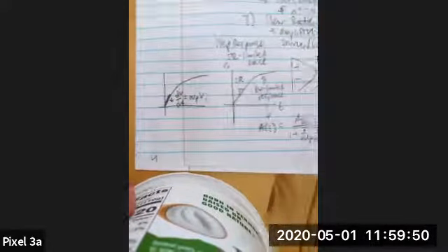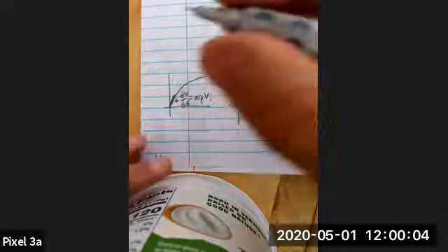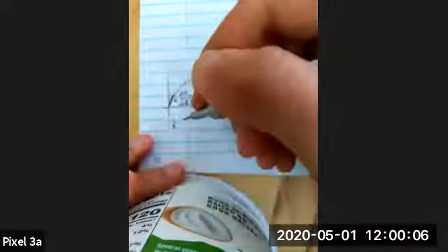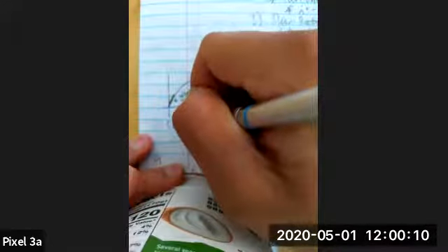So if we want to check whether an output response will be slew rate limited or bandwidth limited, we can just check to see which one of these is minimum. So if the SR is less than omega p times VI here, then